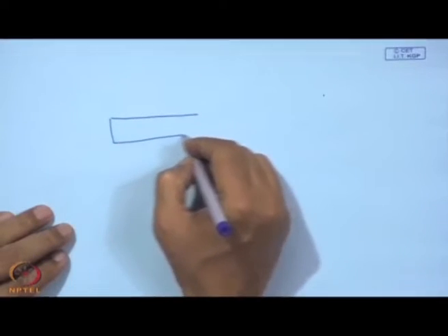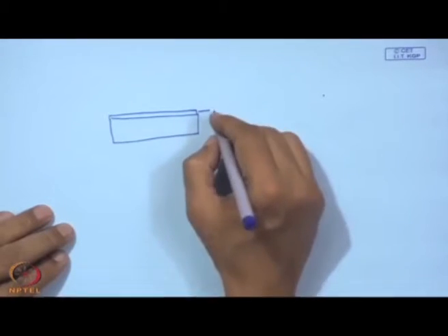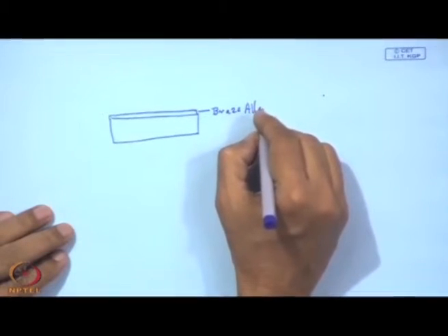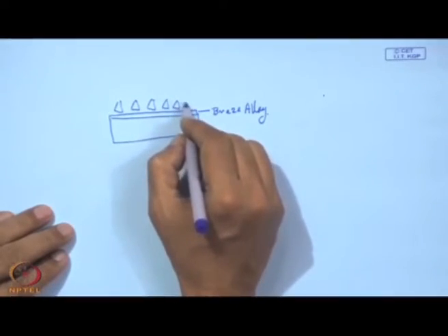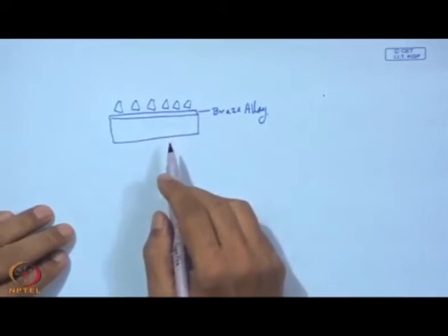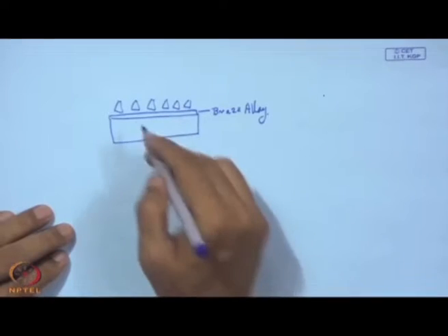Here we can do something very interesting and intelligent. Ordinarily we have a substrate, and then we put one layer of braze alloy, and over that we put the grits, and this is just a temporary attachment, and later, by wetting and bonding, these grits are anchored and bonded to the substrate.